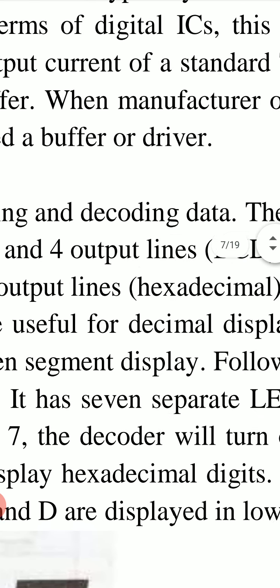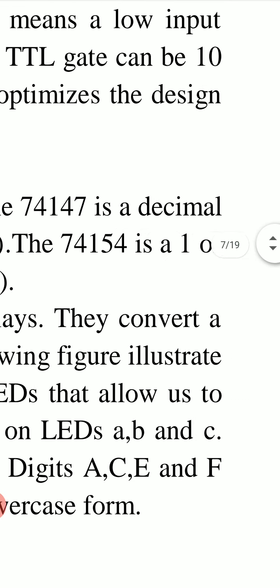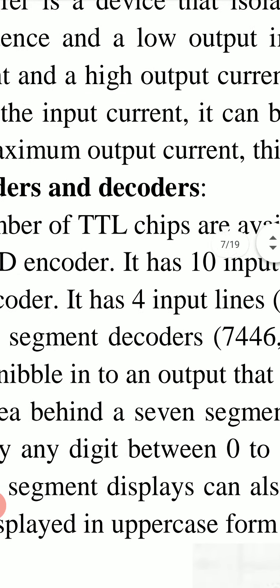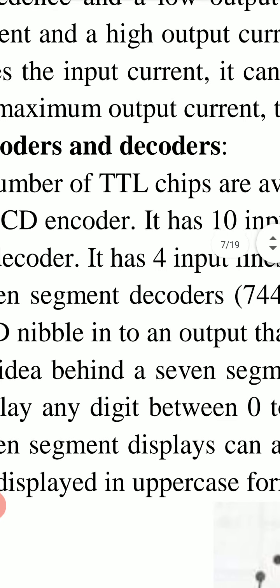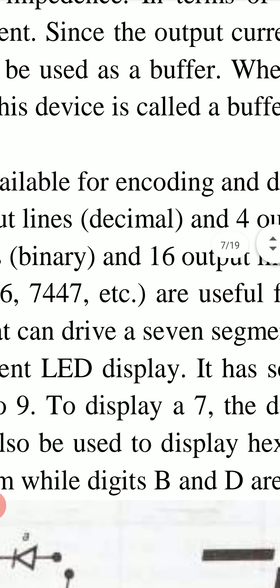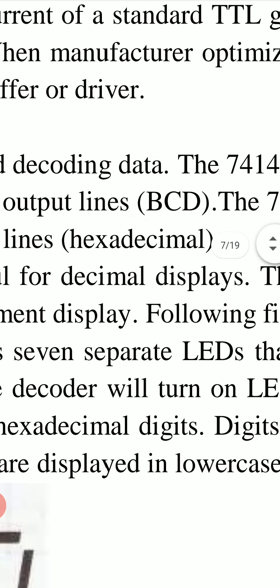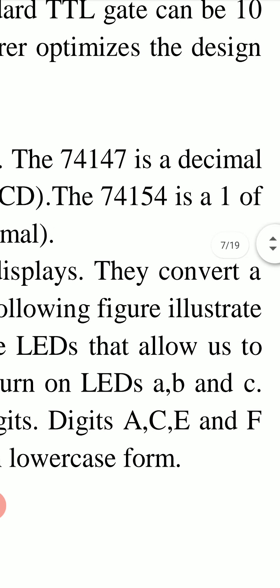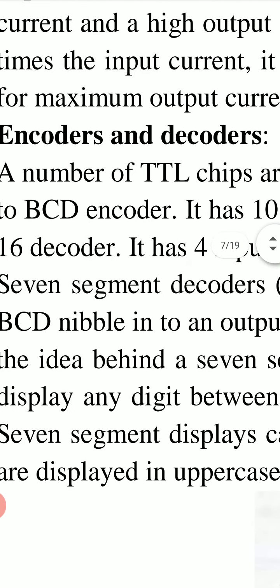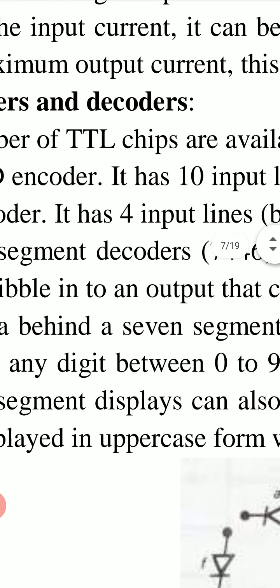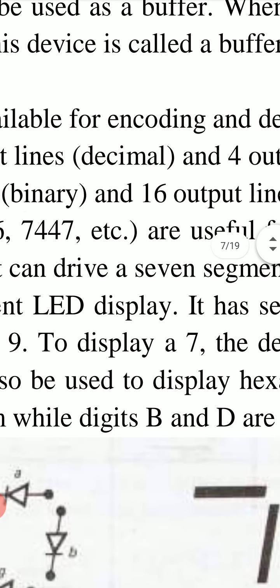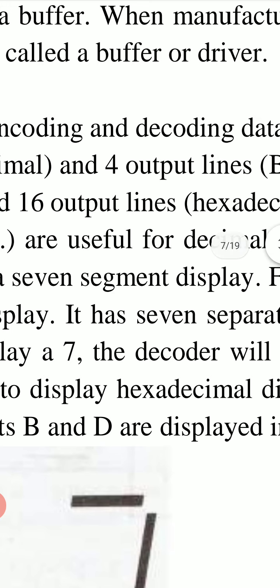Since the output current of a standard TTL gate can be 10 times the input current, it can be used as a buffer. When a manufacturer optimizes the design for maximum output current, this device is called a buffer or driver.